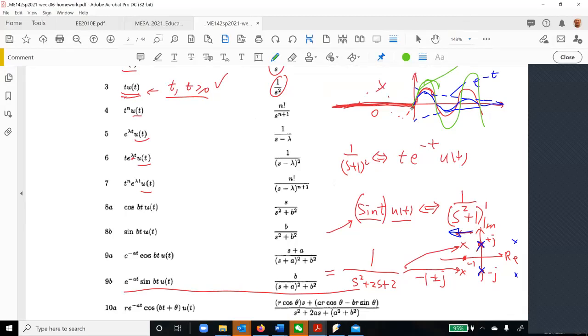So blow up, you have blow up, okay? So that's a question of stability. You can see that if your poles are located in here, everything will be damped because there's an e to the power of minus t here. But what if you have something on the right hand side? Then it will blow up. So in simple words, you just check where your pole is located, then you will know whether the system is stable or not stable. Okay.